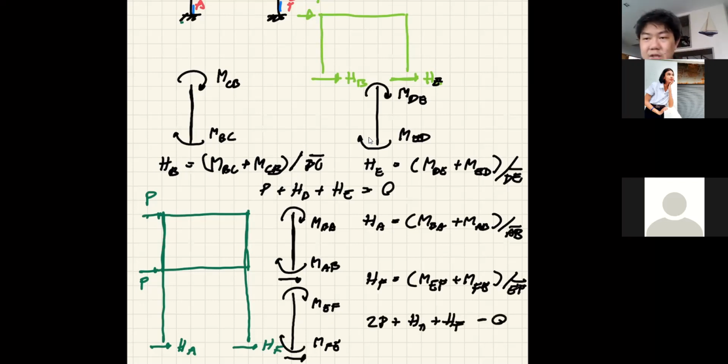So of course, you would expect the shear at the base to be greater than the shear on the column on the second floor, and so on and so forth. So that's why your columns get bigger and bigger towards the ground.